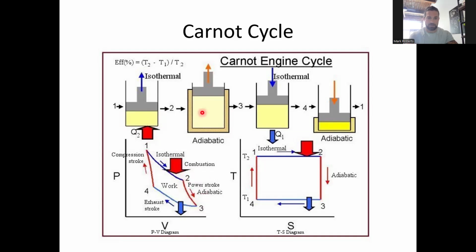The adiabatic component is where the piston just keeps moving until there's an equal pressure from inside and outside. And then once we do the cooling, this would be like releasing the exhaust to the environment. Once we let out the hot air and the system cools, we have this isothermal compression part of it, and this is the amount of work that's required. So we are compressing it, so decreased volume, increased pressure right here.